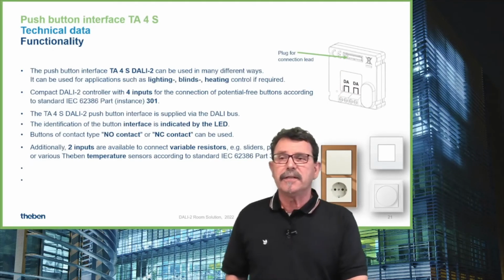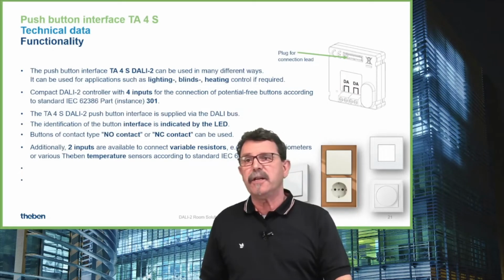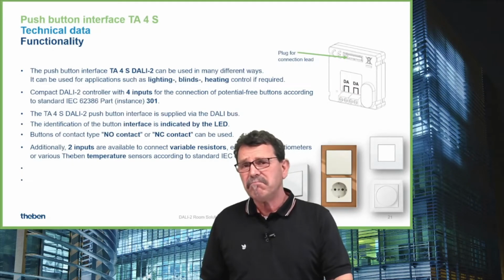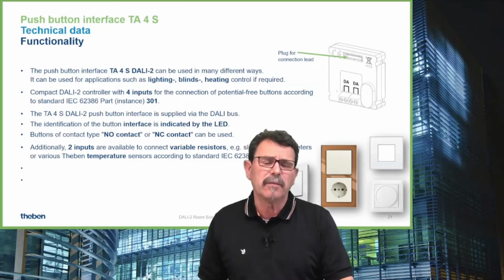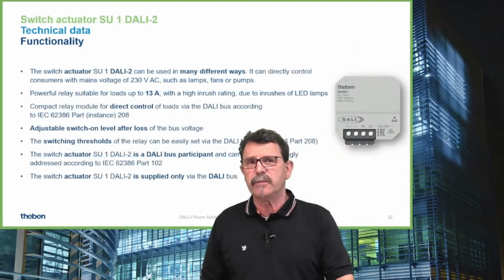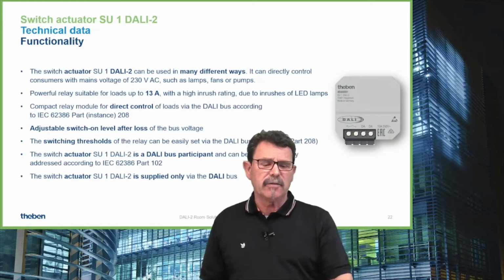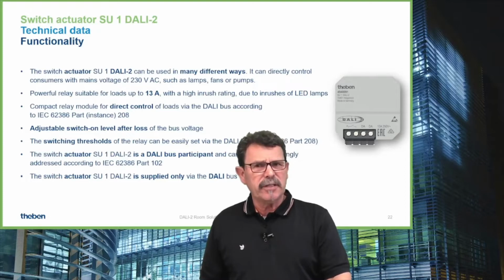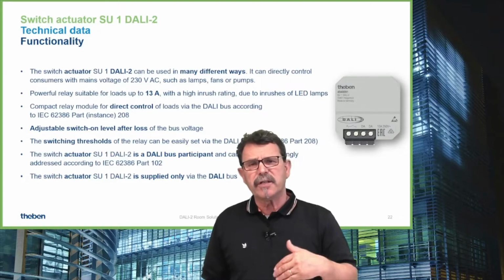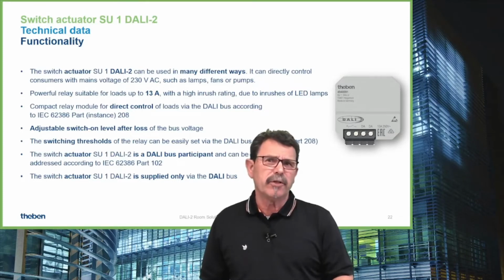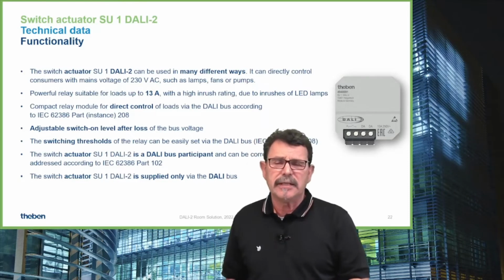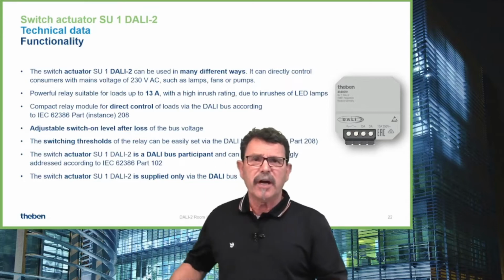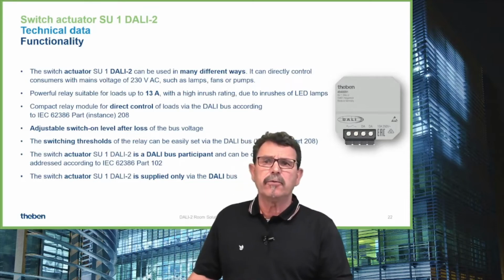And you have the choices finally in regards of the design. You can adjust if you want to have normally open, normally closed. In some cases there is a respective demand. In regards of the switching power of the relay, we put a specific technique inside to avoid damages due to the inrushes of, for example, LED lights. So we have a high inrush rating in this relay.